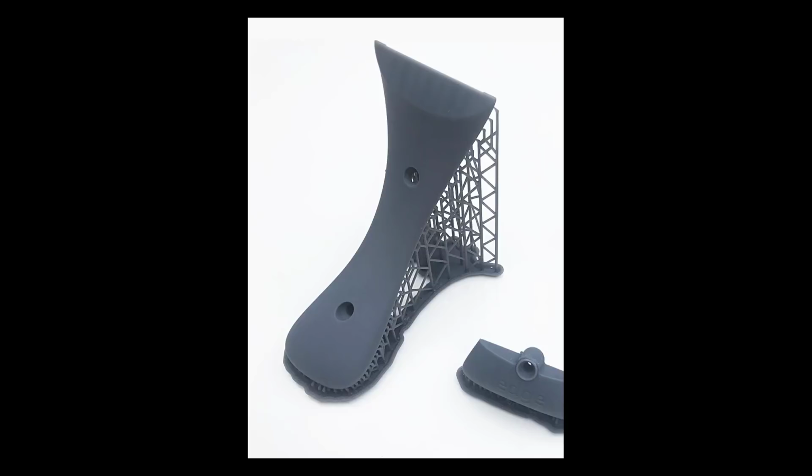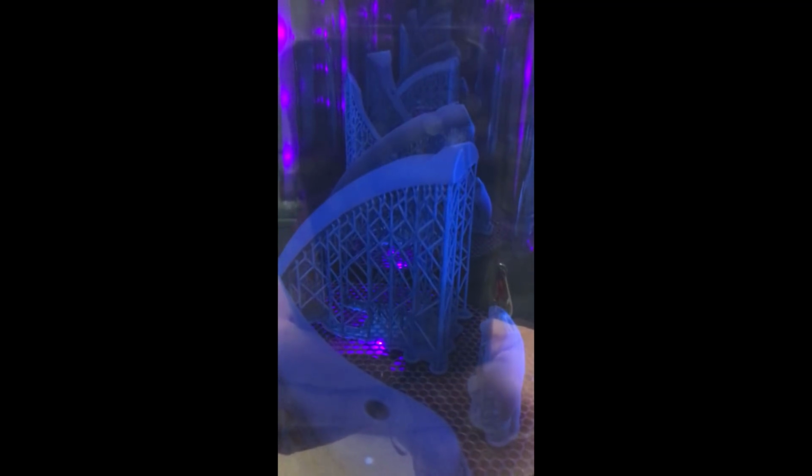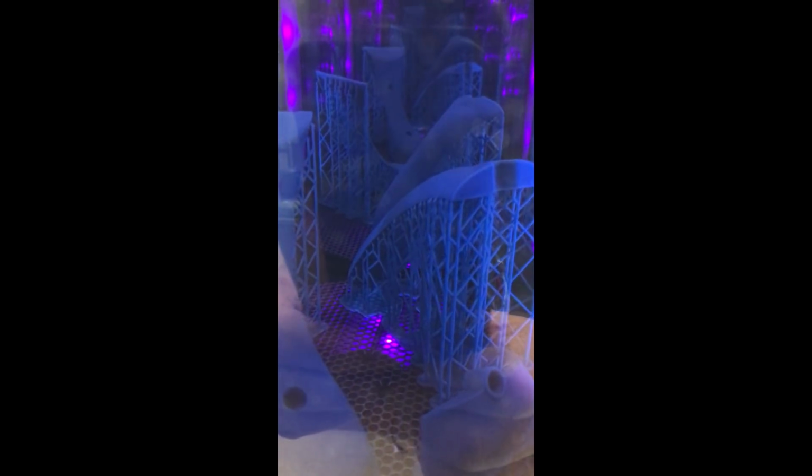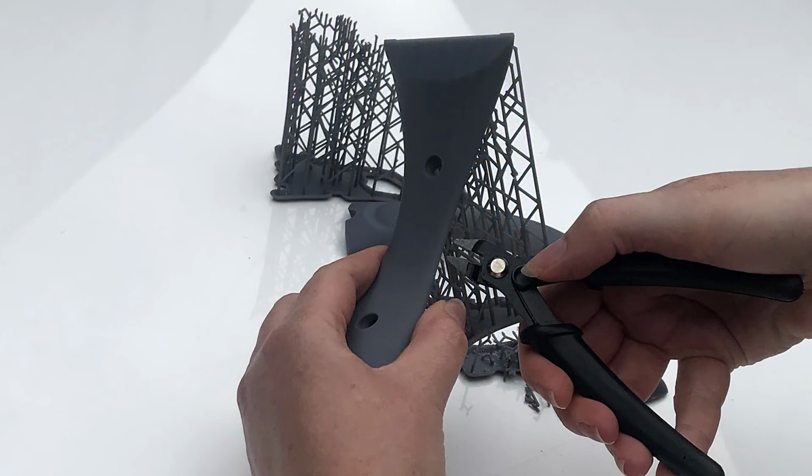Here we're using standard resin, but because our aim is to create a functional, working prototype that will be assembled, disassembled and handled frequently, we are going to use the form cure. The curing process helps us maximize the performance characteristics of the resin, and in this case we will be curing at 60 degrees for 30 minutes. The final step is to remove the supports from the parts.